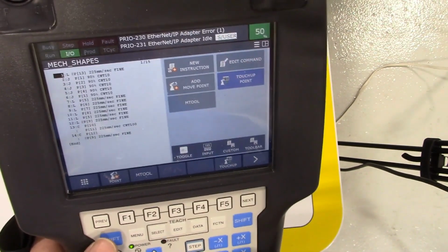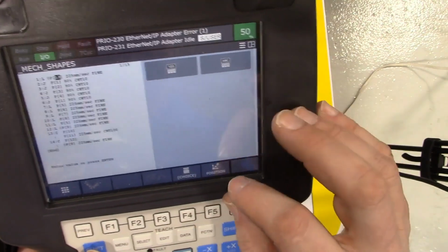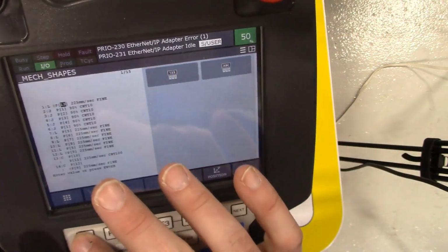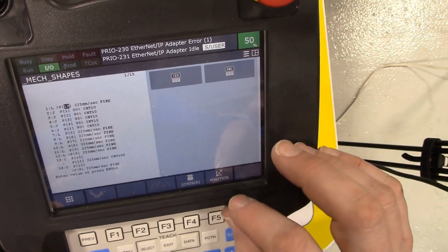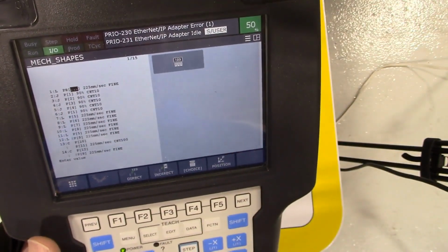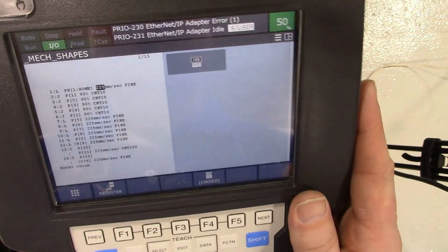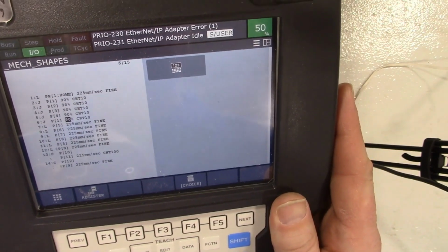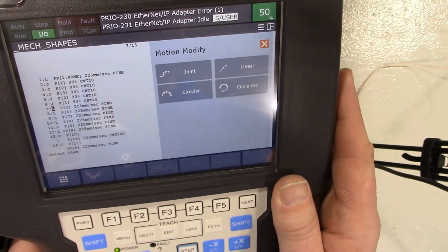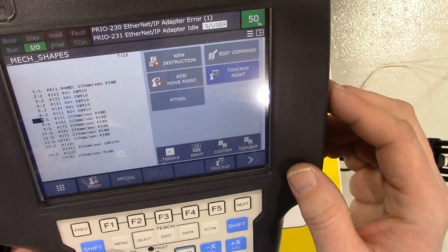And that one, I'm going to change from the type here. I'm going to make that into a position register, and go to position register number 1, which I know is the home. So it starts at home, runs out, does these 4 points in joint mode to make that outer square. Then the next one, we need to have it go back home as well.